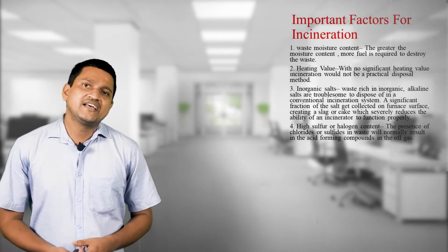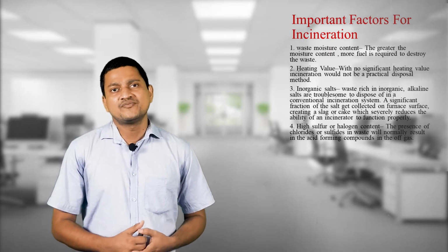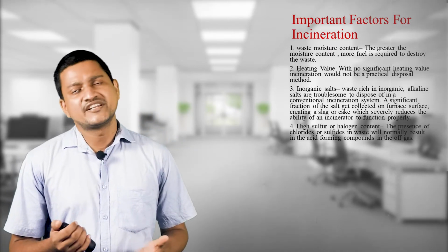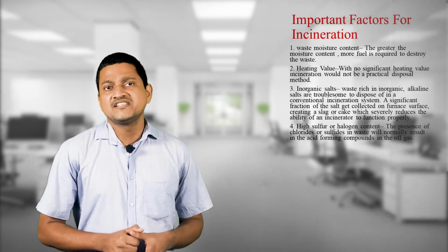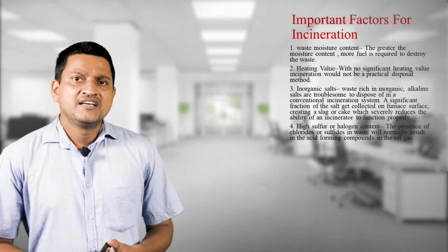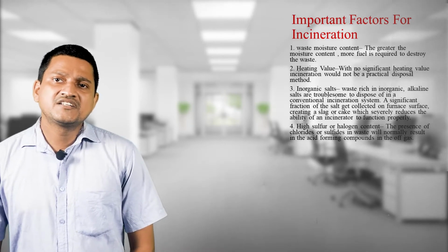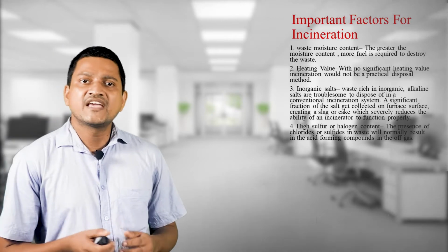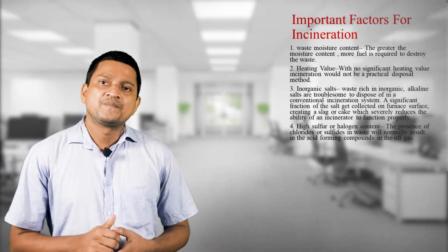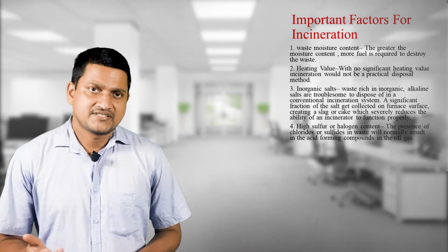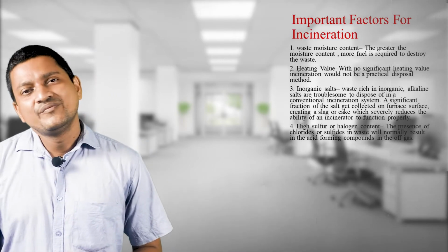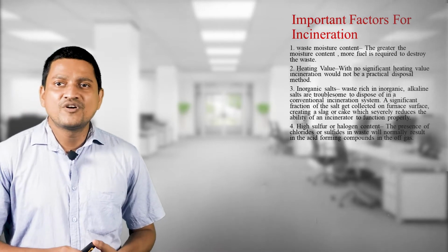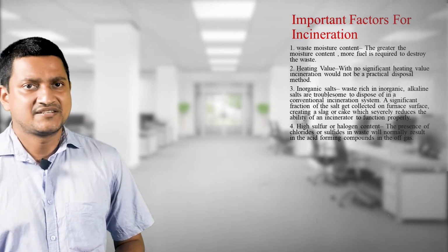The next topic is the important factors for incineration. What are the different factors that we consider if going for an incineration process? First, the waste moisture content. The greater the moisture content, the more fuel is required to destroy the waste. If the waste is dry, we can minimize our fuel. Next is heating value. With no significant heating value, incineration would not be a practical disposal method.